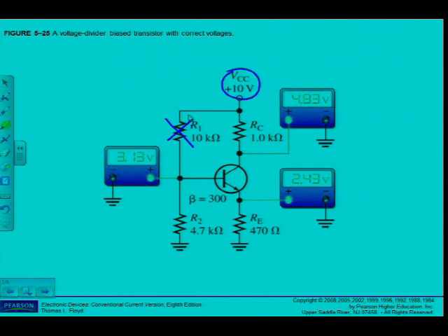no voltage is going to reach my VB. My VB is going to determine my biasing current IBQ. So if there's no voltage there, what's going to happen? IC, would I know? IC is equal to what? Beta DC times IB. So IC is going to be 0.